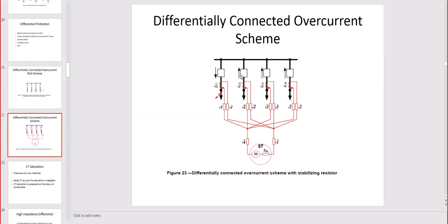It will not have direct sequence only. It will be a very severe change. That's why the sine wave is not there. The current is not a sine wave anymore, because the zero sequence and reverse sequence, added to the direct sequence, will make it look very distorted.